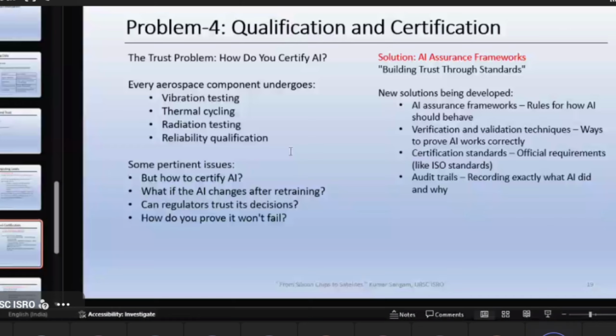Qualification. Material: let's say you're using solder A, that was qualified. We want to move to solder B, so qualification. Method: we were using the reflow process, now you want to go for an advanced method. Again, qualification. Machine: let's say you're using machine X, now you want to use machine Y because of some issue. Again, you go for qualification.